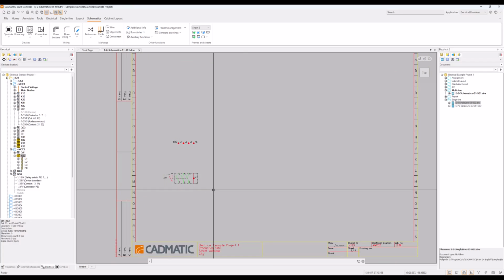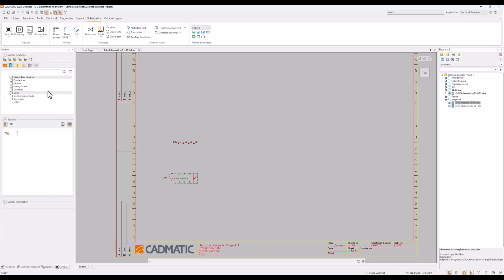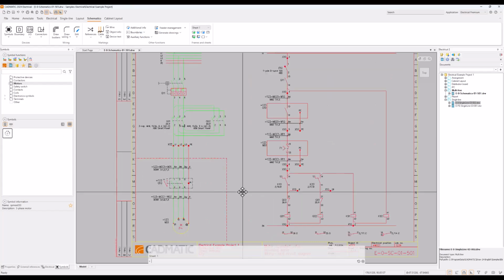One thing that we didn't create was a motor into the database. And the motor can be found from the symbols. Open the Symbols window when you are on Schema tab. Select Symbols. Well, we can actually have an exercise. You can either go to electrical symbols or you can go symbols in current drawing. And you should be able to find motors and only one motor symbol since we have the motor in the page number 1.